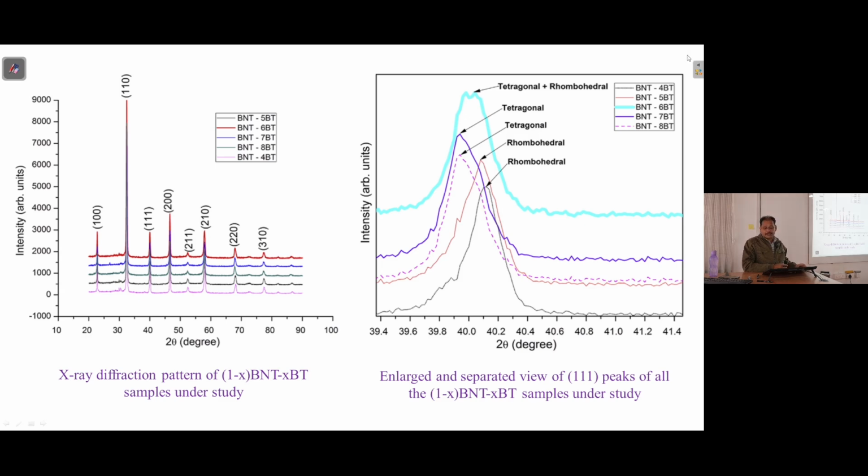Yeah, so the point is for this particular one, we have both the phases. Here you have tetragonal phase for the higher fraction of this, and here you have rhombohedral for lower fraction. But for this particular one, both coexist. Because of that, this peak splitting confirms that this is happening. So choosing this one composition is for the reason that because of the coexistence of these two phases, this tends to give better properties as compared to the other two combinations. So that way it is a popular material.